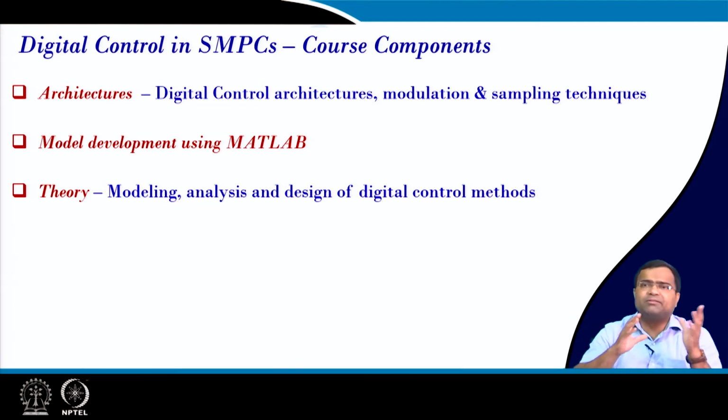For example, in our previous course on control and tuning methods, we learned that with a small signal modeling technique, if we get the linear transfer function model, obtain the step response, the AC coupled response, and add the DC component, and compare with the actual switch simulation, the model reasonably captured the behavior up to 1/10 of the switching frequency, and beyond that the model starts diverging. But in this course we will show such a model may not even be sufficient for digital control, even under low bandwidth.